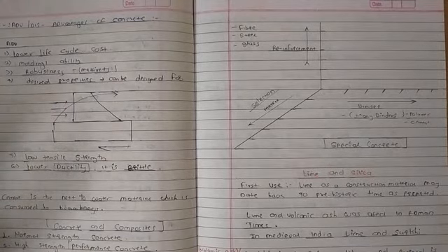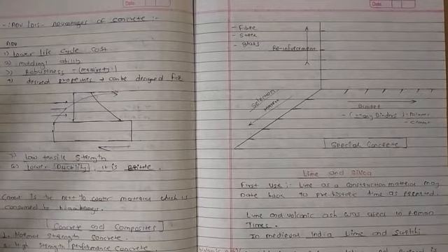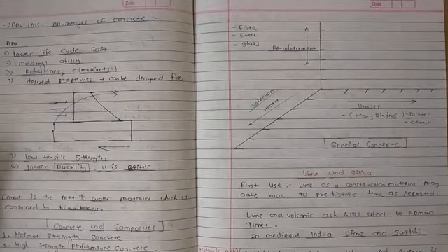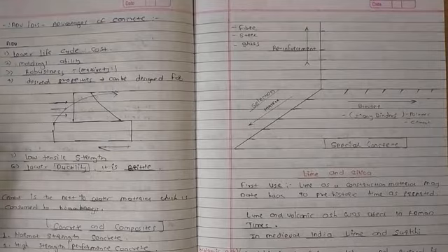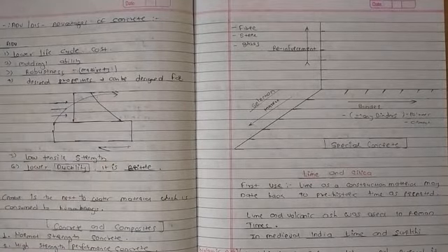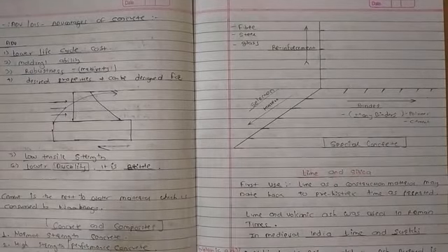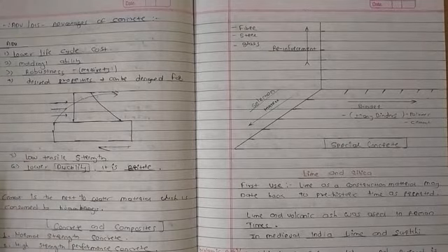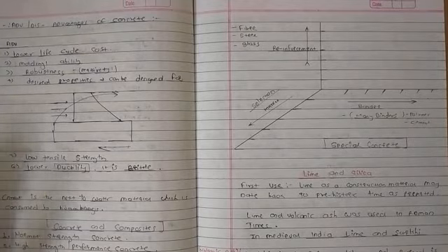Surkhi comes from the clinkers of a brick. If we burn the clinkers, there are residues of a soil having silica content. After being heated, they are still on the ground, having a high content of silica, and they are burned at a very high temperature. So they have the silica, and the silica with water and lime produces a hard mass like a stone. That is very important. Note down, please: with silica content, surkhi, and with lime and water, they form a very hard mass.